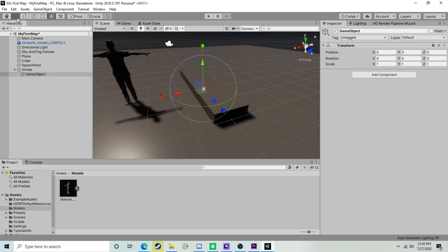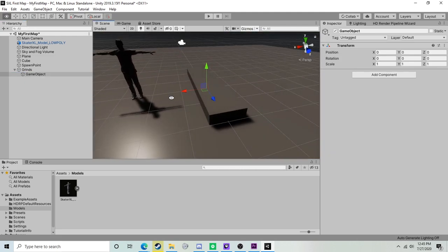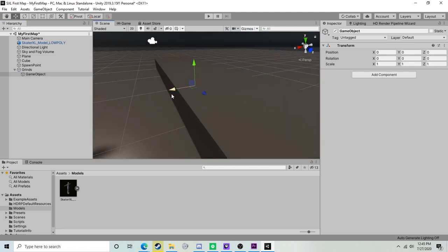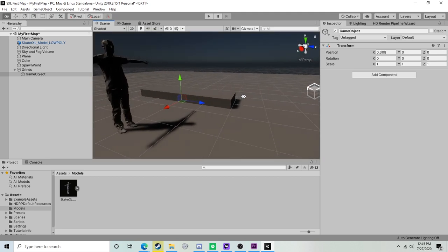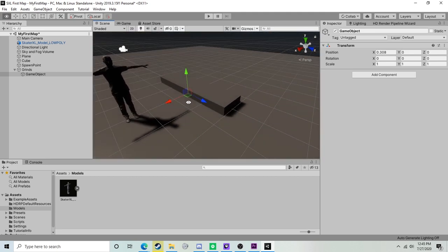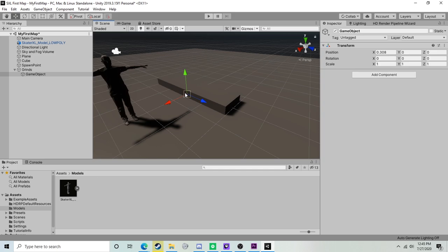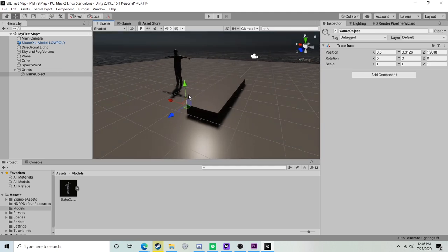This object is going to be our very first spline. So I'm going to go ahead and position it to align with that edge. A quick tip for this is I can hold V while in the 3D viewport to enable vertex snapping mode and snap it to this corner vertex. And then I can go ahead and reposition it or just leave it there. Either way is fine. The exact position of this doesn't actually matter.